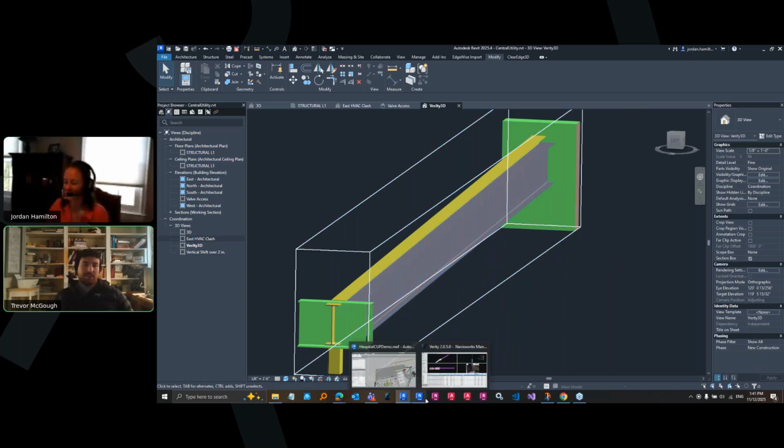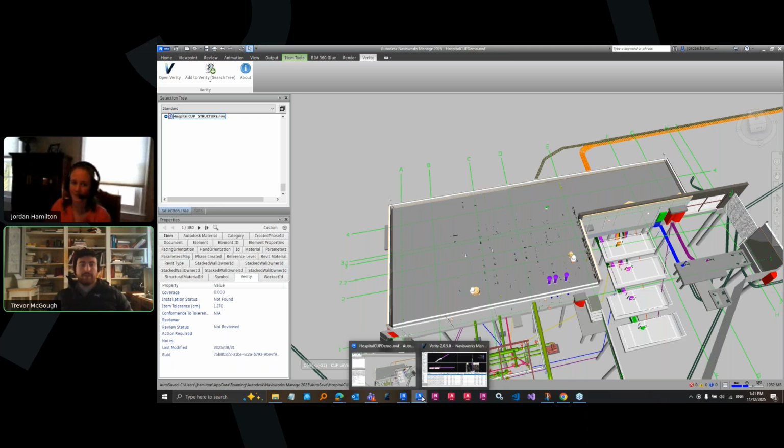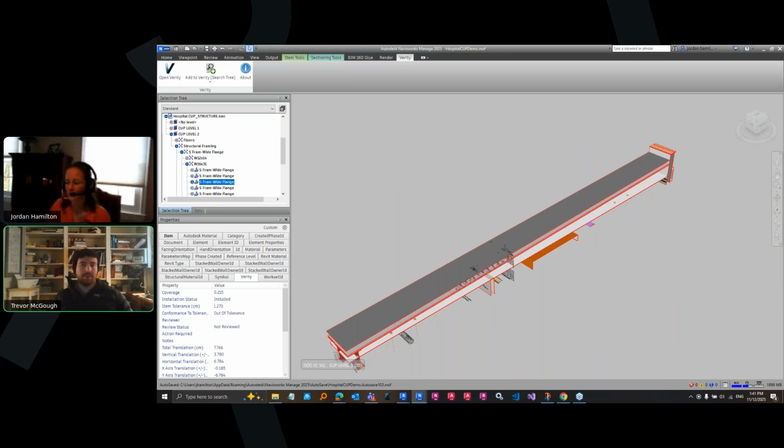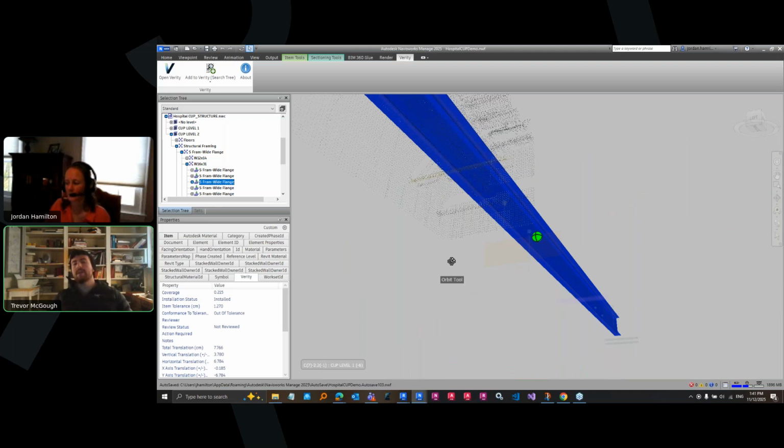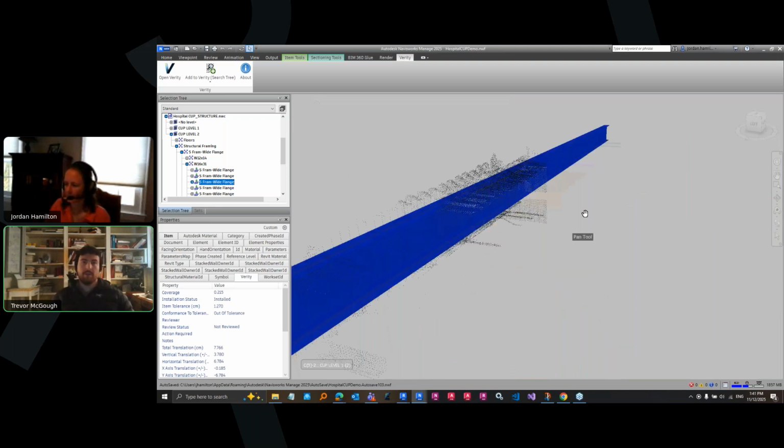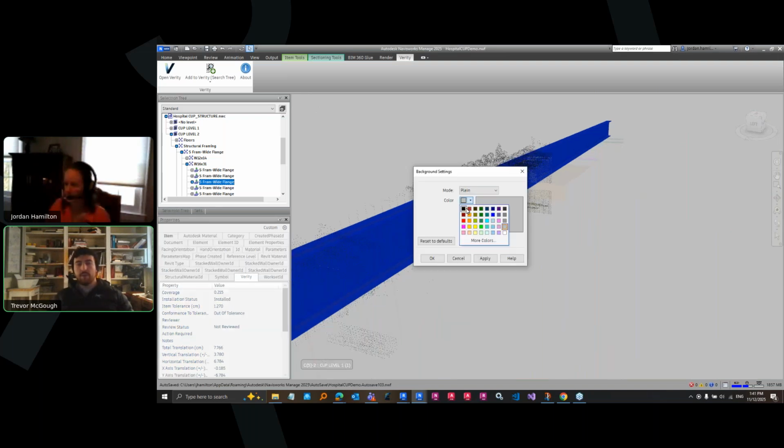Yep, no, this is one I really want to highlight because, again, everyone wants the as-built inside of Revit. So while we don't change the original model, we can create that in-place family, which is a copy showing the as-built location. Part of the reason is there are some limitations, especially with connected systems, about moving those things around. But what we want to do is place that as-built copy right there for dimensioning purposes and so on, so that you have that directly inside of the BIM. So back to you, Jordan.